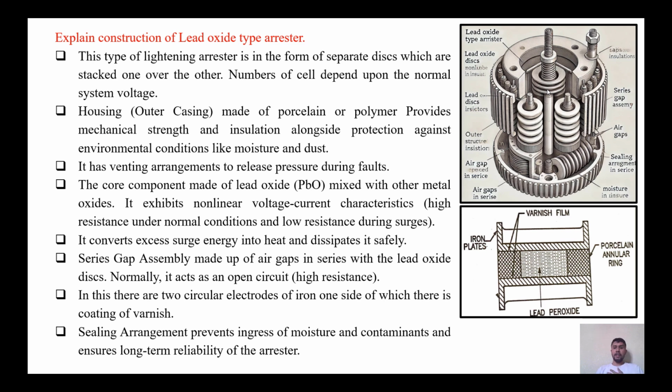Series gap assembly is made up of air gaps. So, as you can see here, this series gap assembly made up of air gaps is in series with the lead oxide disc. Normally it acts as an open circuit, meaning offering a high value of resistance in series.